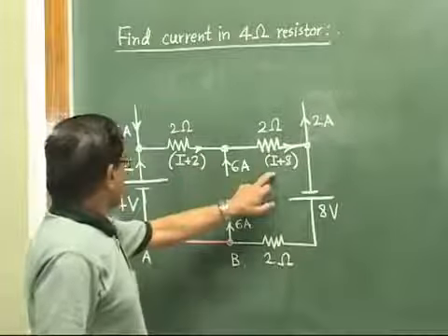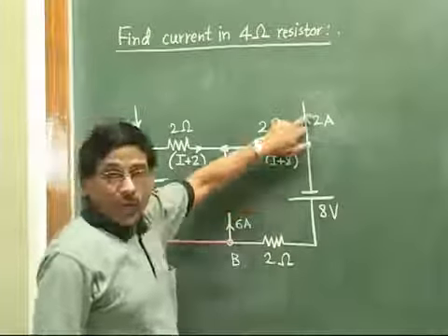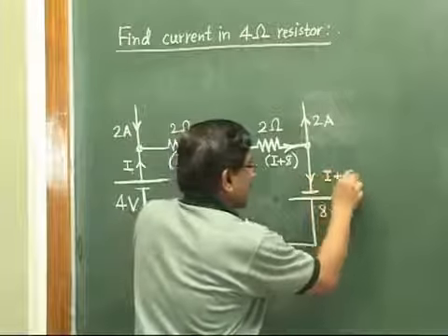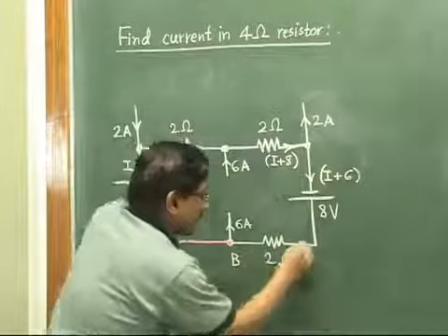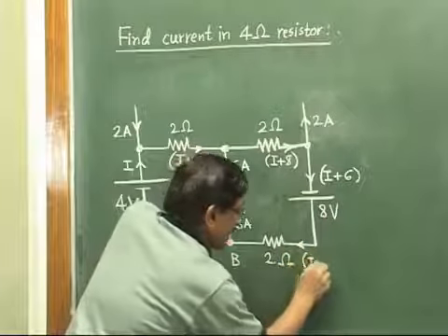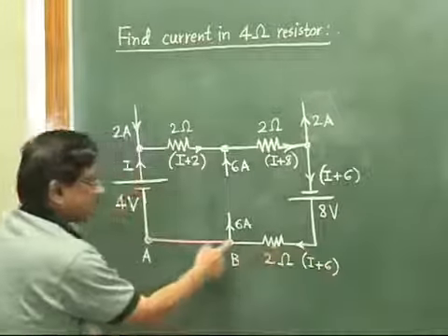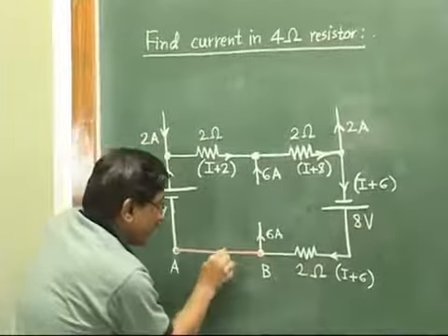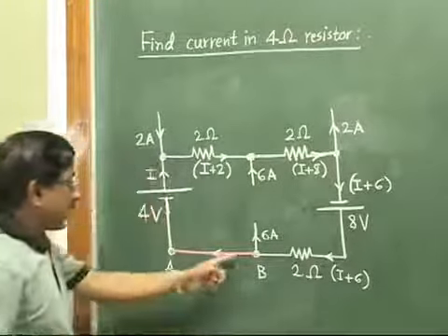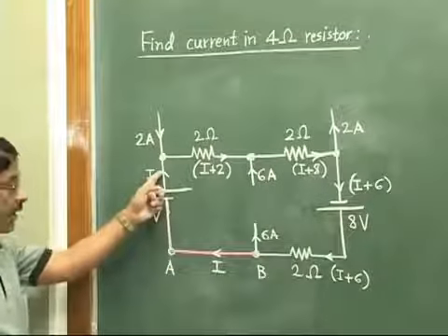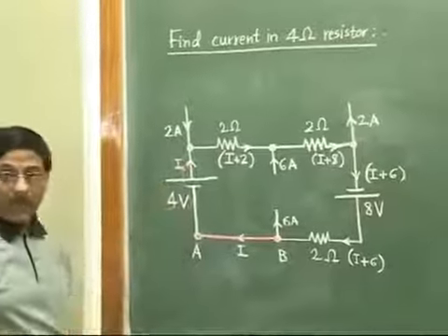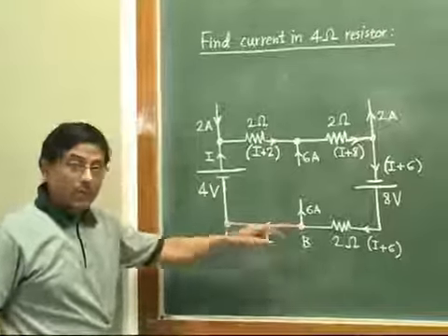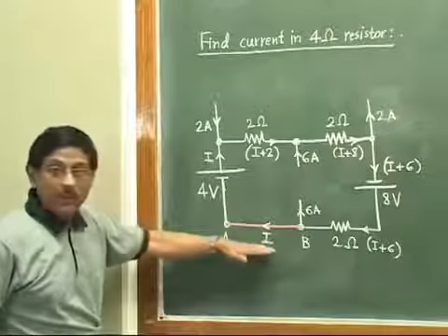Then I plus 8, 2 ampere goes away. So current coming down here would be I plus 6. This I plus 6 will come down here. Here also it will be I plus 6. Now out of I plus 6 reaching here, 6 is going out. So current I will be moving ahead. Okay. And you will find that this I matches here. Our current distribution is proper. So as per our current distribution, a current I is flowing through short circuited branch. So we are interested in finding out the value of this I.